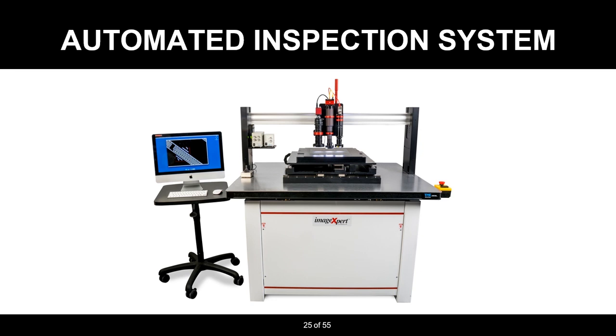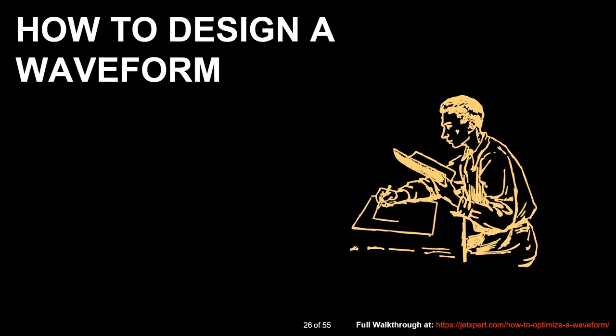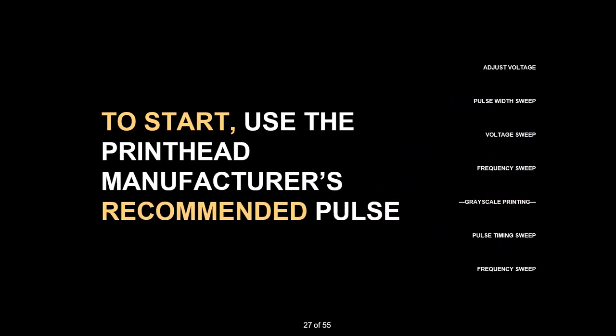So now we'll get into the nitty-gritty on how to design a waveform itself and the process that you would go through now that you have your target of what you want for speed, number of satellites, volume, etc. Most print head manufacturers, when they sell you the head, have some sort of recommended waveform that they might outline in the user manual or is just general common knowledge. And so as a starting point for any waveform optimization, it's wise to use that default waveform.